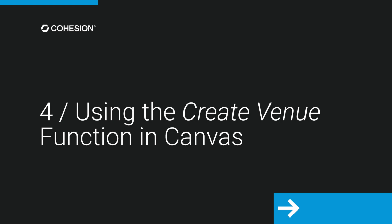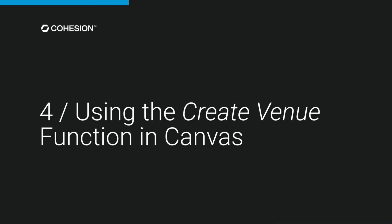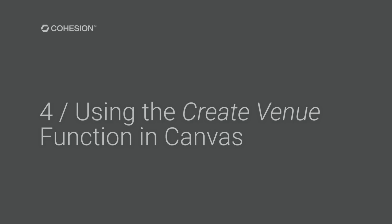Traditionally, this means recreating the design in the new venue model so that new pinning and aiming angles can be established. The Create Venue function in Canvas makes this process faster. Once imported, venue, system, and production elements can be easily adjusted as a group to properly align them within the venue model. Once everything is aligned, you can make system adjustments specific to the new venue.